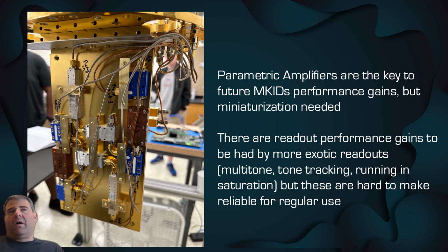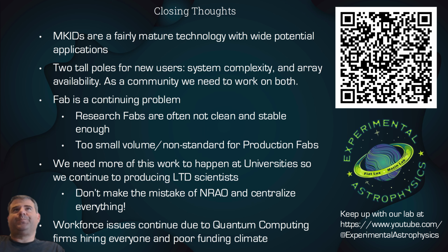Also, think hard before you make something too complicated for your readout. There are performance gains to be had by more exotic readouts like multi-tone readouts and tone tracking and running the resonators into saturation, but these are hard to make reliable for regular use on an instrument.